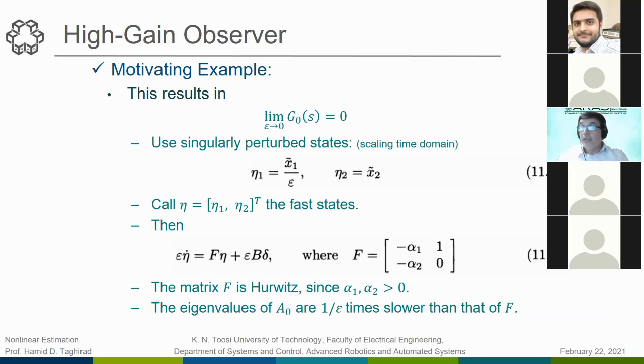But in nonlinear control, it's not like that. You can design the high-gain nonlinear observer here, and then you need a Lyapunov-based controller design to stabilize the system, if you need stabilization. It's not necessary to be robust. It could be robust if the uncertainty of the system is large. It could even be adaptive. It could be any means, but it should satisfy the stability condition. Thank you. You're welcome. Any other questions?